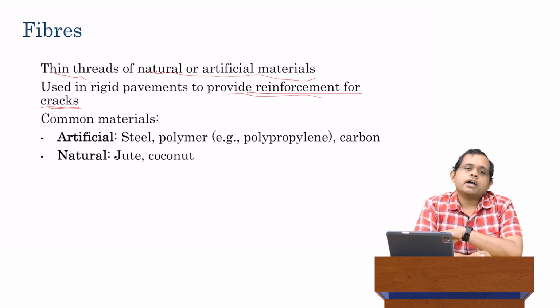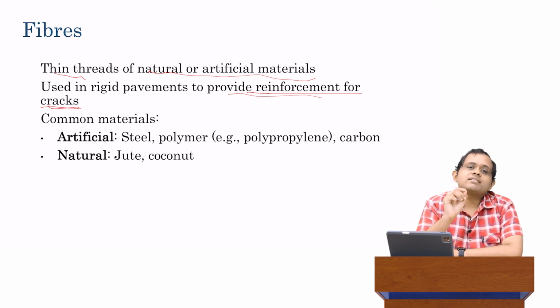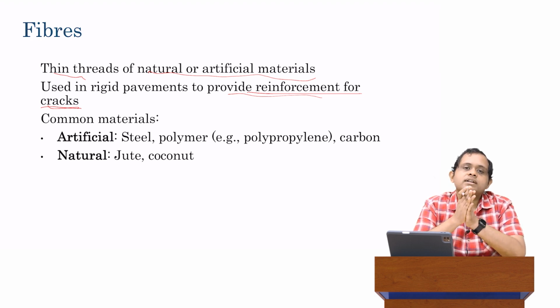They do not affect the formation of cracks or the initiation of cracks. They affect the propagation of cracks. So in rigid pavements, fibers provide reinforcement for cracks. That is, once a crack develops, once a crack already forms, then these fibers bridge the cracks. They basically make sure the cracks stay together and the crack width doesn't open up too much. But they don't prevent cracking as such.